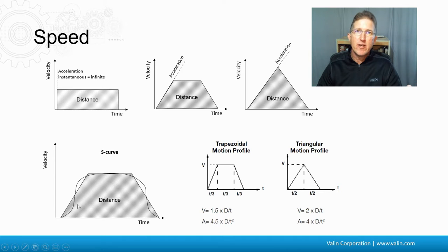And then if you really care about smoothness, then we might be taking a look at an S-curve profile in order to reduce the amount of jerk caused by the points where the acceleration changes. In which case, we end up with a really steep acceleration ramp here, which is more force or torque at the motor, and so we have to take that into account. So the speed really has to be about the motion profile. It has to be defined with possible accelerations, distance versus time, what's important. And oftentimes, I'm just asked, I want to go this speed.